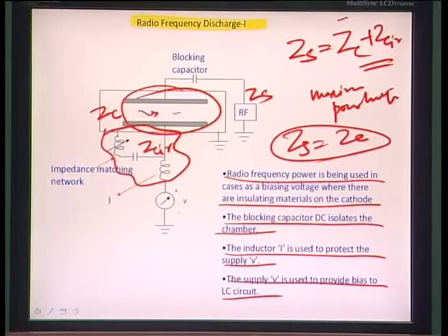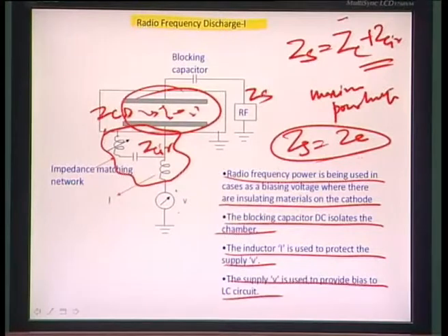the quality or the dynamics of the ions which are in this chamber. It is a dynamic process. You have ions, you have electrons, you have some gas molecules, you have varied dielectric constants, and they may not be uniformly homogeneous as a property, and therefore the ZS here, or the source impedance, is changing frequently.